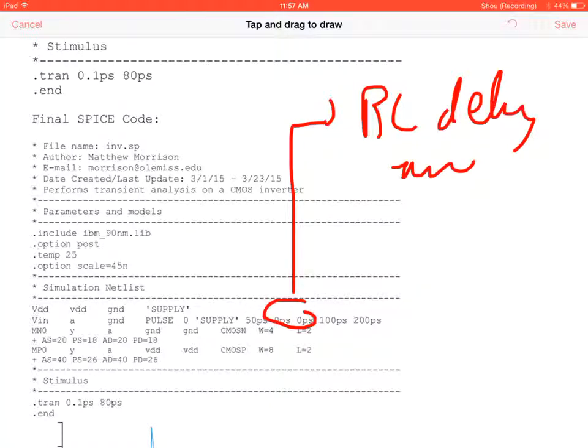We also know that you have to have a certain amount of time in order to create the channel in the PMOS and NMOS transistor, right? So what's happening is you're going to have this time, if you recall, where the channel in the PMOS is closing and the channel in the NMOS is opening. So if you don't allow sufficient time for that to happen, what's going to occur? Wrong input, so you get wrong output. Yeah, you're going to get some of these little spikes, right? So it's not going to transition properly.